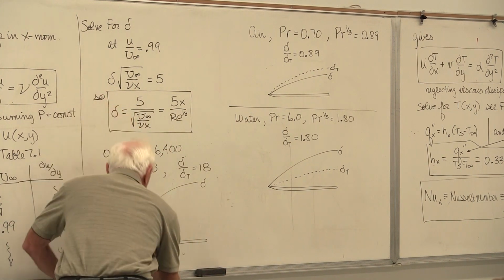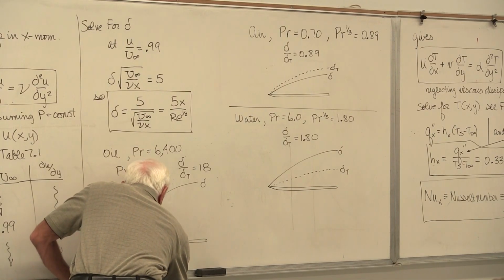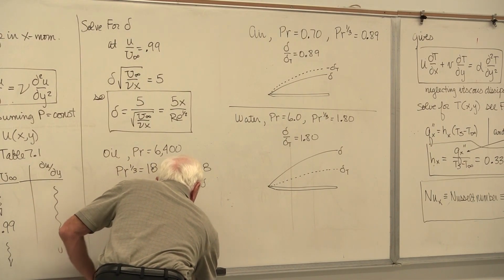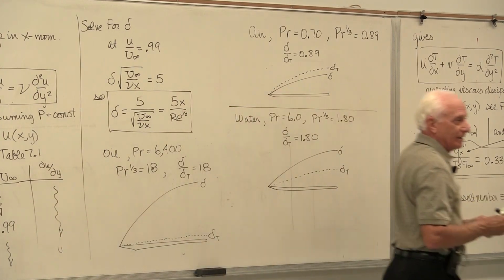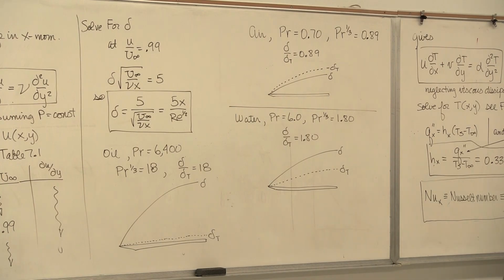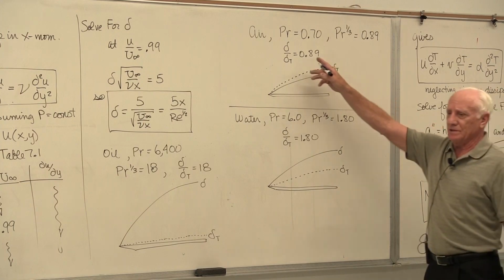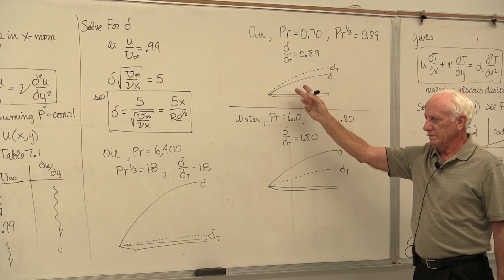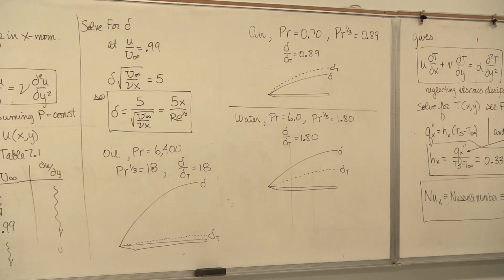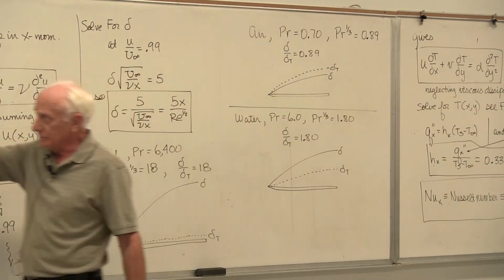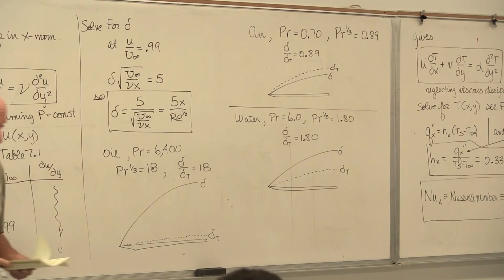Here's a temperature boundary layer down here. Boy, the velocity boundary layer is tremendously thicker than the temperature one. Of course, oil's very, very viscous. Air's not very viscous at all. No surprise. Oil, real viscous. Water, 2-to-1 ratio at normal conditions. So that shows how those thicknesses, delta T and delta, vary in the picture right there.